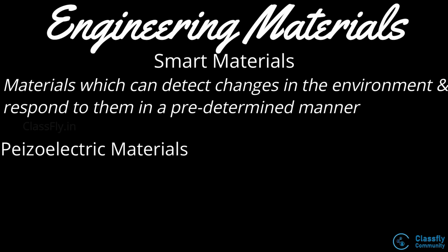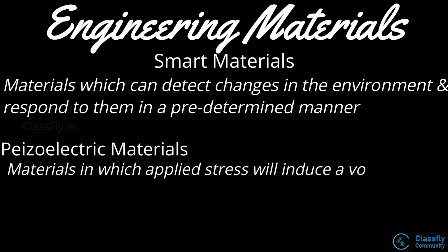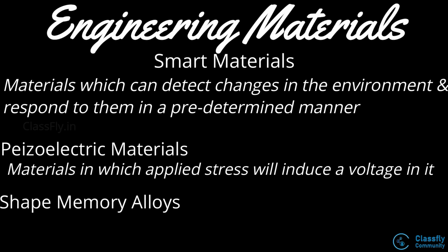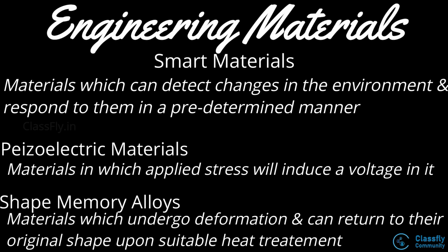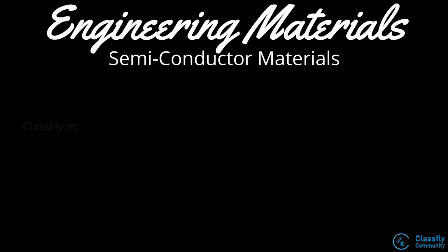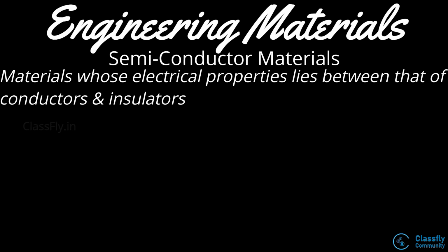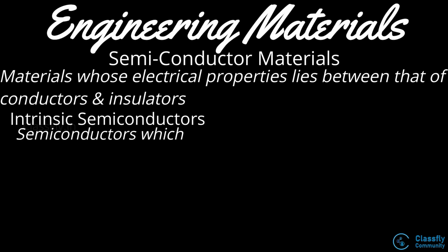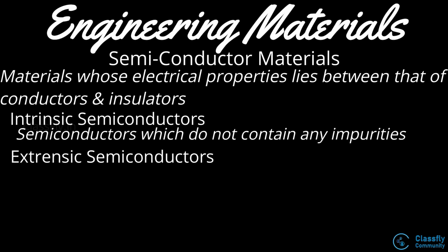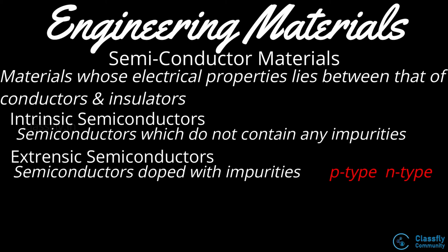Here we studied about piezoelectric materials, that is the materials in which the applied stress will induce a voltage, the shape memory alloys, where the materials can undergo deformation and will return to their original shape and size upon suitable heat treatment, and also studied about the semiconductor materials, where the materials whose electrical properties will lie between that of conductors and insulators. Here they are further classified into intrinsic semiconductors, which do not have any impurities, and extrinsic semiconductors, which contain several amount of impurities.